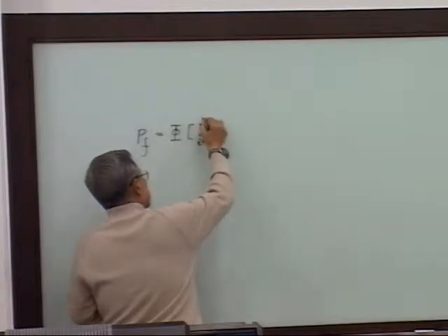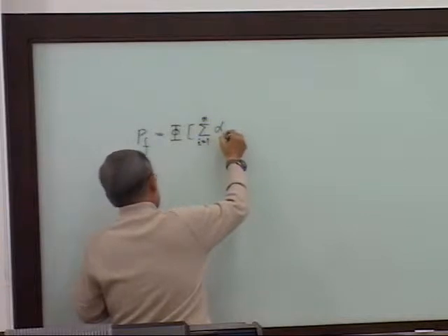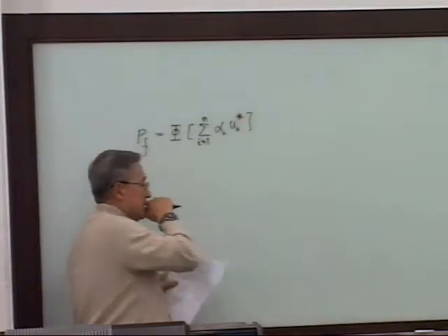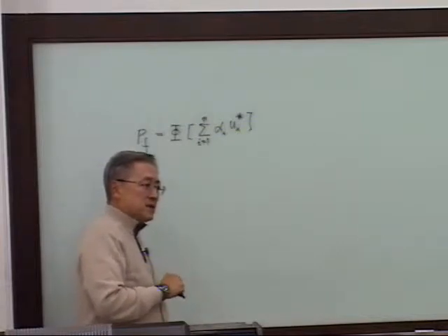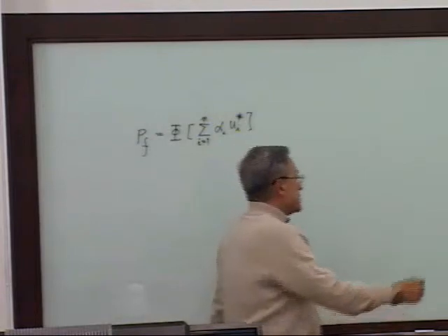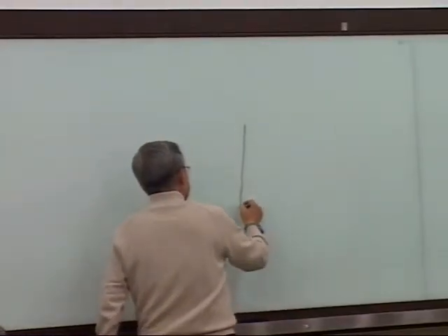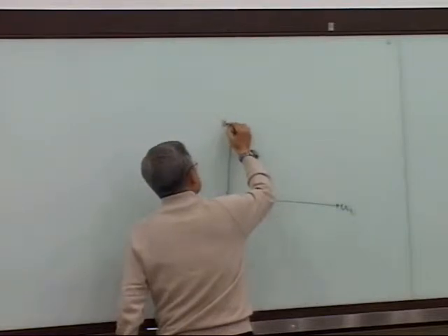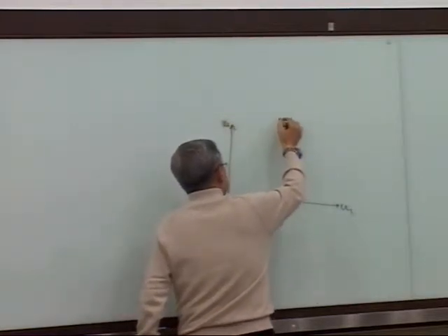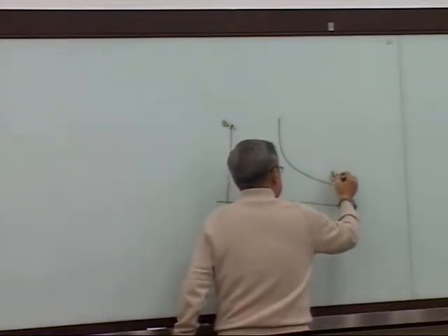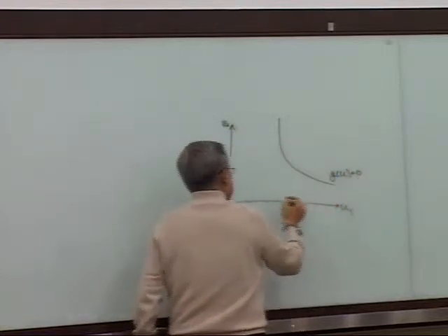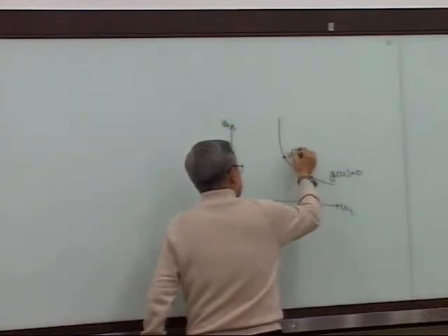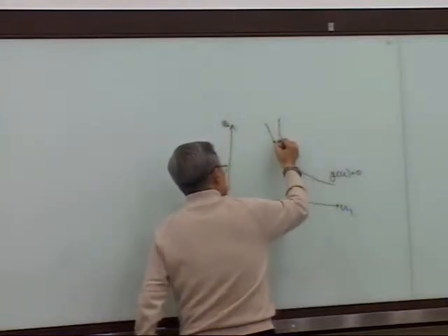This is something like page 13 in that area, with alpha i and U_i star, and the U_i star is really the MPP point, the most probable point. If I redraw this after the transformation, here is the G function. This is the origin. If I say this is U star, it's really the tangent point.